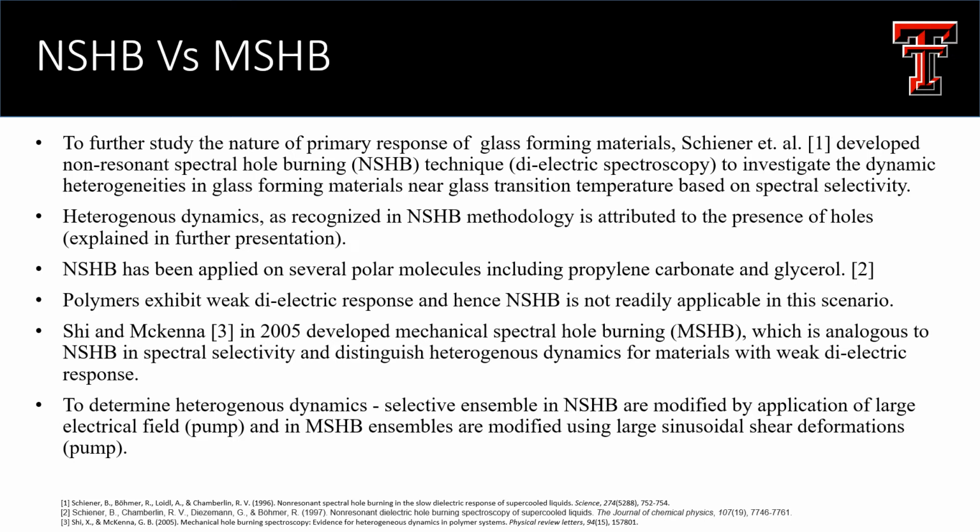NSHB has been applied on several polar molecules including propylene carbonate and glycerol. But polymers, on the other hand, exhibit weak dielectric response and hence NSHB is not readily applicable in this scenario. To address this issue, Shi and McKenna in 2005 developed mechanical spectral hole burning, which is analogous to NSHB in spectral selectivity and distinguishing heterogeneous dynamics, for materials with weak dielectric response. To determine heterogeneous dynamics, selective ensembles in NSHB are modified by application of a large electric field, which is referred to as pump, and in case of MSHB, ensembles are modified using large sinusoidal shear deformations.